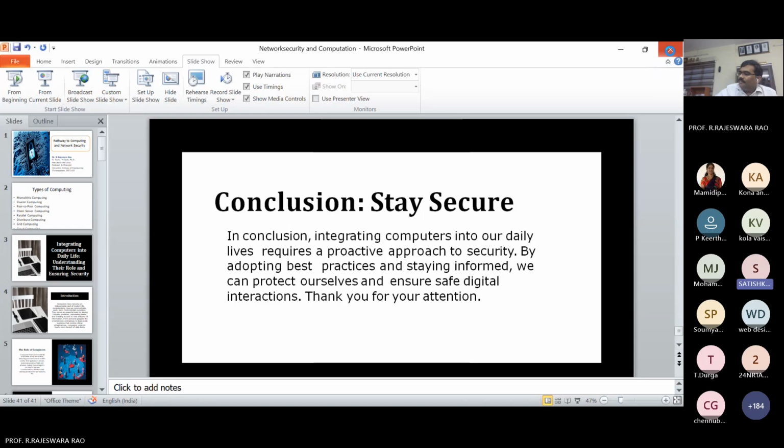This is C++ code. I have written pin number 13, so that means the data will be sent to the LED by using this pin. Once we write this code and start the simulation, you can see the LED is blinking. See what I have written in the code: delay is 1 second, which means the LED lights up for every 1 second.